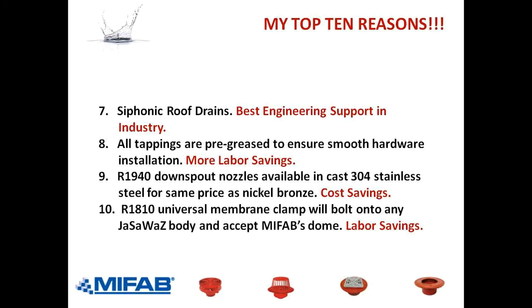And we see siphonic roof drains continuing to grow. Basically, we're reducing the diameter of the pipe so that we can use smaller size pipes, smaller couplings, smaller pipe supports, and have the pipe work flat, not sloped. That can be a webinar for another day.